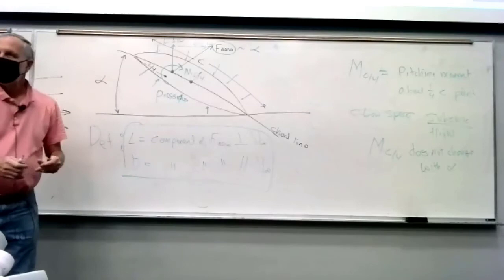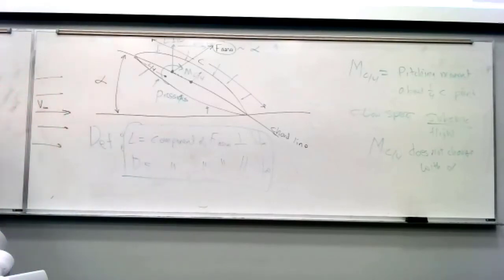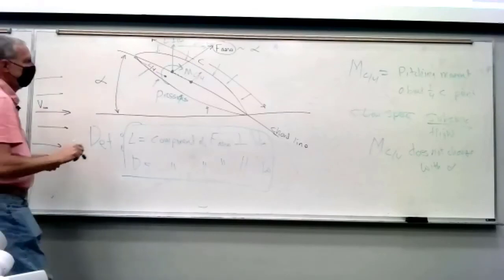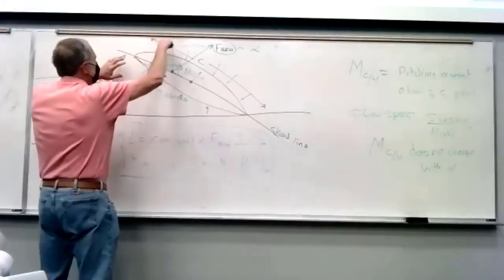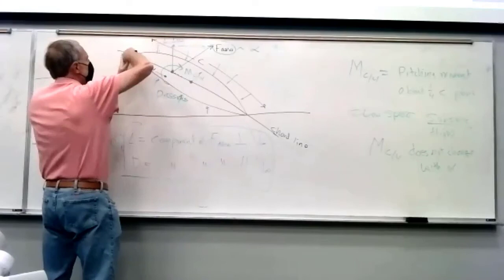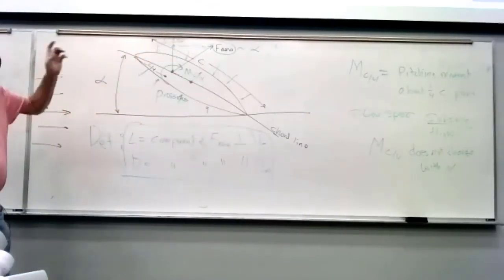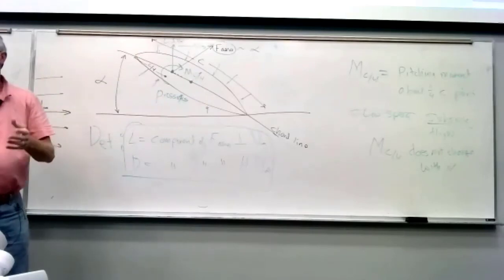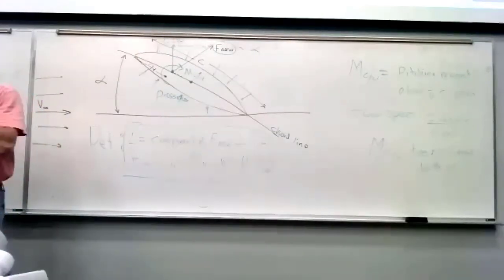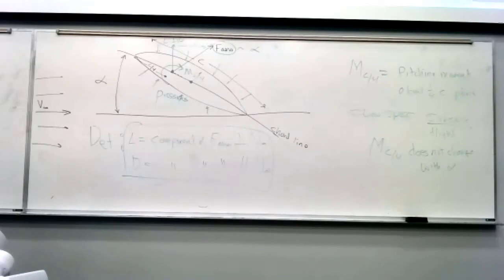So as you approach the speed of sound, your F arrow moves back. The pressure forces change if you start getting shock waves. And when you go supersonic, the whole thing is behind the shock wave. And it just changes the pressure forces, so the net force acts further back. Does it ever get behind that halfway point? Go faster?